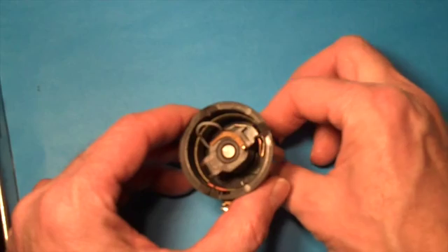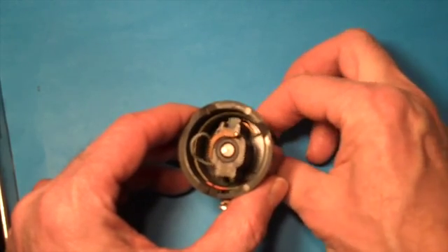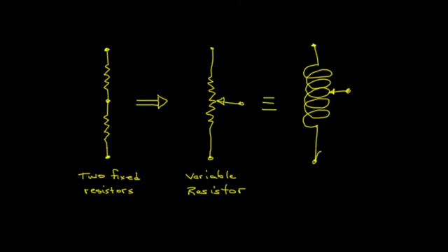As the sliding contact spirals down the coil, the resistance between the contact and the end of the coil nearer us increases. So the contact represented by the arrow in this diagram changes distance between the 2 ends, one distance increasing while the other decreases, and the resistance between the pointer and either end changes in proportion.